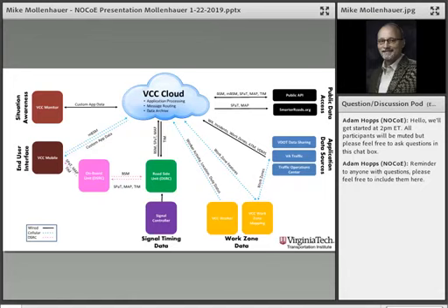We have a connection to a public data sharing portal called smarterroads.org. That is a VDOT data sharing site, so we push SPaT and map messages and now traveler information messages out through that website, and they can be received by pretty much any third-party developer who wants to get them in near real time. Also connected to the cloud, we have our roadside DSRC units, and on those 30 intersections where we're connected to the signal controllers, we are pulling timing data from the controller into the roadside unit so that we can generate the SPaT messages locally.